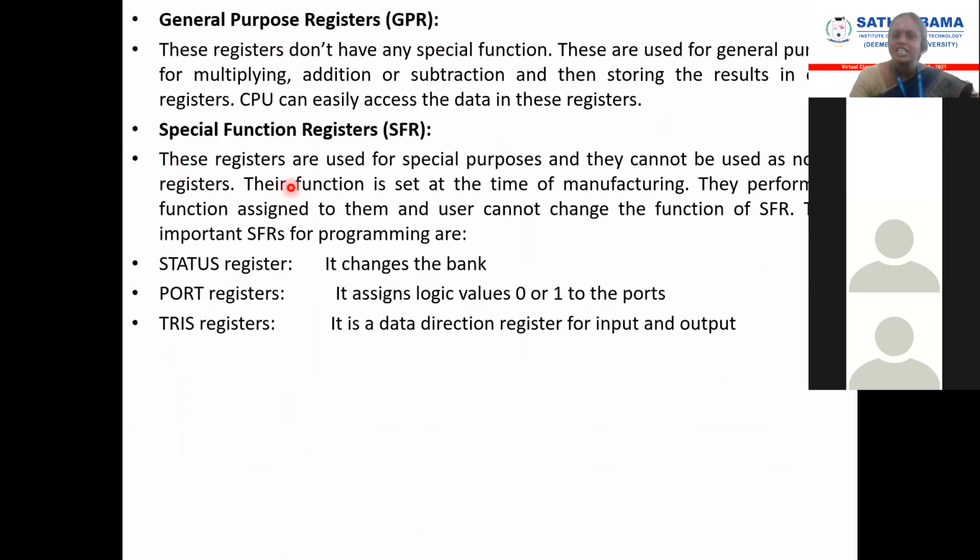General purpose registers, special function registers. General purpose registers don't have any special function. They are used to perform arithmetical and logical operations only. I can access my data through this general purpose register. Special function registers are not like that. They are specifically used for special functions, like ports or serial communication registers, timer registers. They are dedicated to that particular function only. The manufacturer itself assigns the functions for that register. We cannot change the functions of the special function registers.